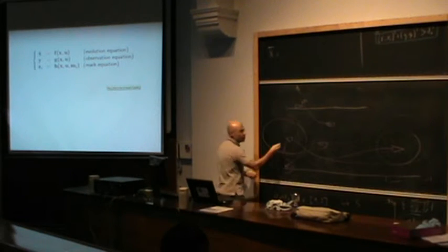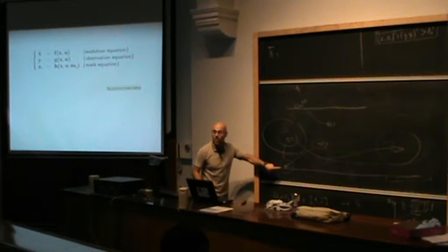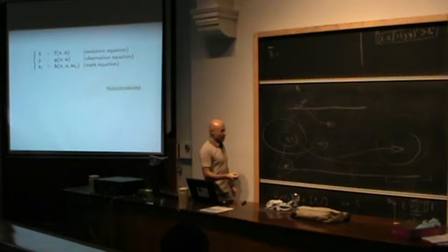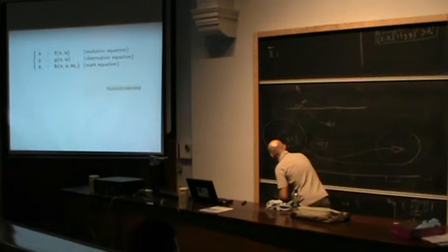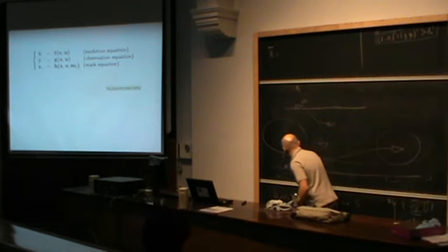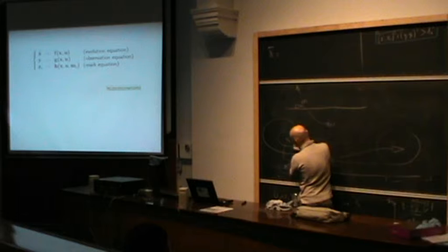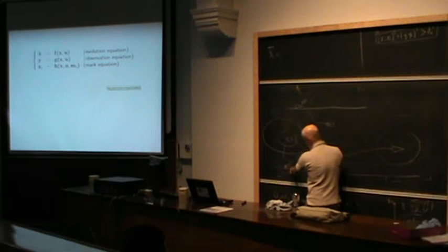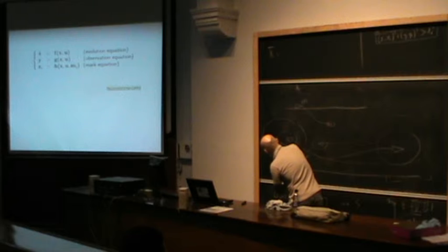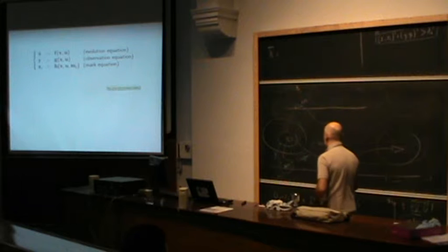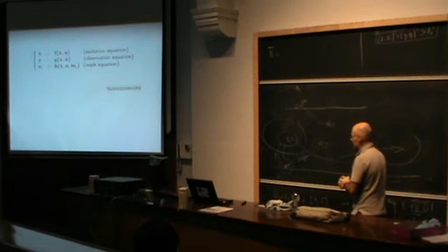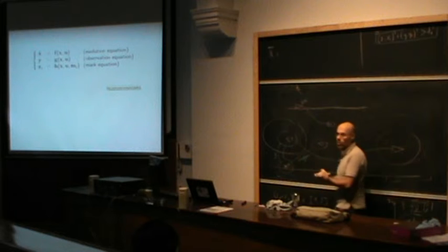So it will be able to correct its position because it sees something it has already seen before. So the first step, when it was here and when it is able to localize the marks on the map, is called mapping. When it corrects its position with respect to a mark, it is called localization. Okay, so that's why we call it simultaneous localization and mapping, because it tries to solve both problems altogether.